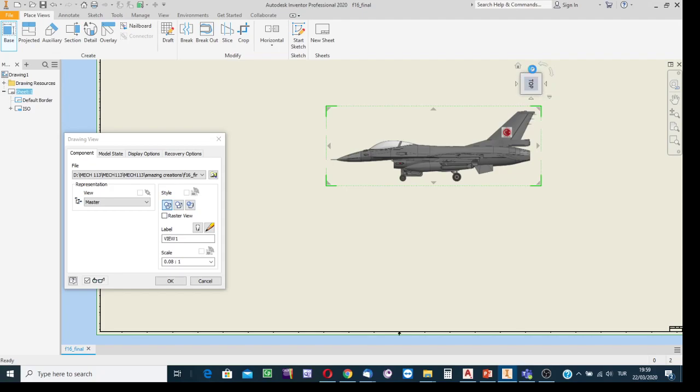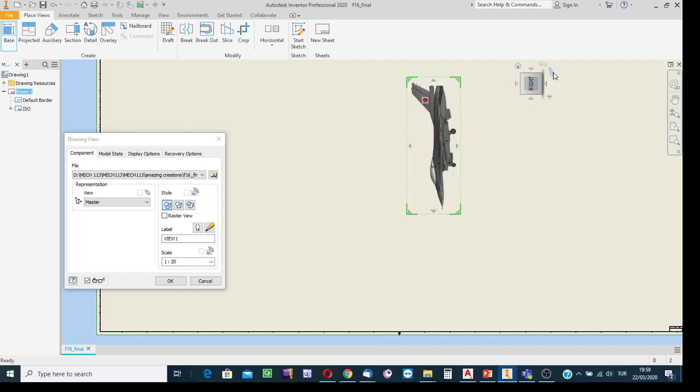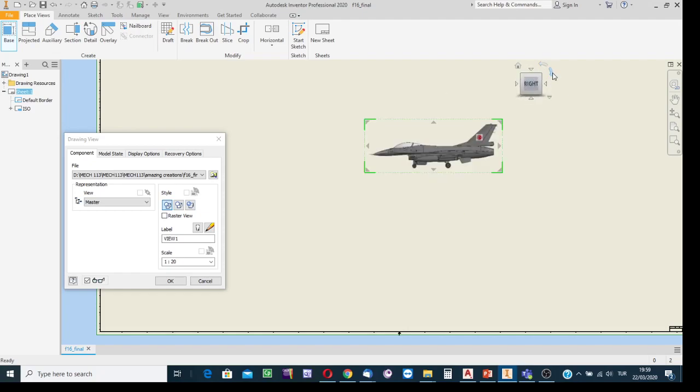Click on this, about the horizontal axis through 90 degrees, or click on the bent arrows, rotated about a perpendicular axis with respect to the screen. You know the function of the orientation cube. Here, making such rotations and directing the selected frontal side of the body as parallel to the paper can teach the software that it is the front side view.